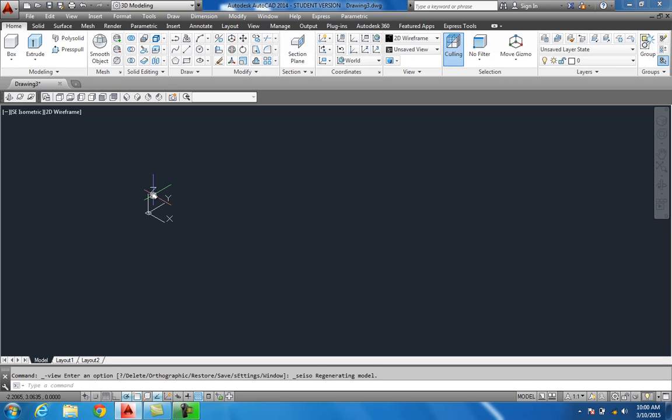Something to remember: when you're working with AutoCAD, it's already default as soon as you open the program up to go to the XY coordinate, XY plane. So you're going to be drawing on the XY plane. Alright, so to start out with this, it's going to be rather simple. Go up here and use your draw and type in 0,0. And you all see how we're drawing in XY? That's default. It's already there. The only time it'll draw anything else is if you tell it to.